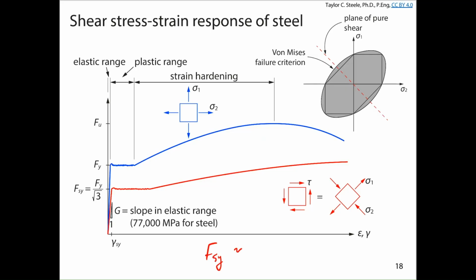And that's going to be important because we're going to see steel beams later on and steel bolts that fail in shear. And so we need to be able to recognize when we're using the tensile strength modified by a factor to account for the fact that we're trying to look at it as a shear strength.